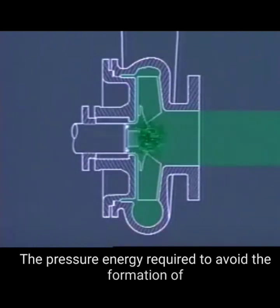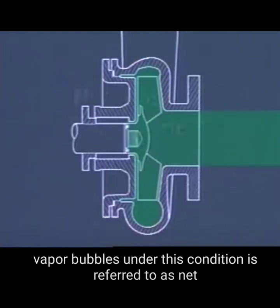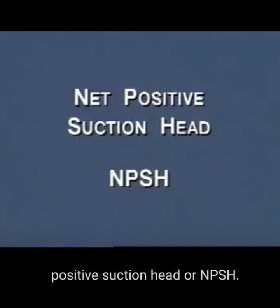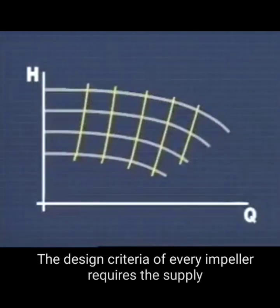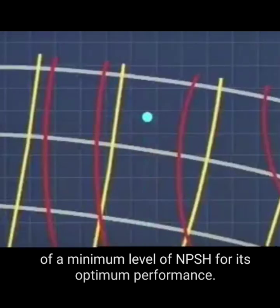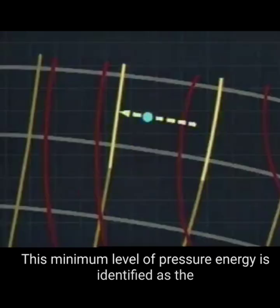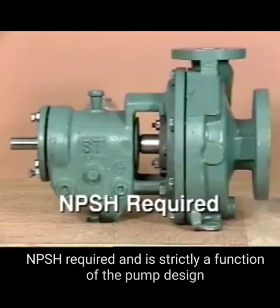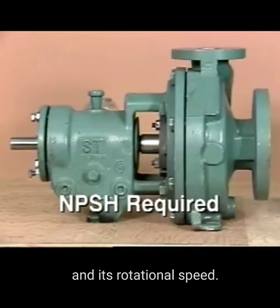The pressure energy required to avoid the formation of vapor bubbles under this condition is referred to as net positive suction head, or NPSH. The design criteria of every impeller requires the supply of a minimum level of NPSH for its optimum performance. This minimum level of pressure energy is identified as the NPSH required and is strictly a function of the pump design and its rotational speed.